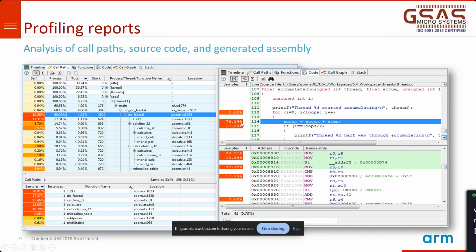So this particular C statement is where the processor is spending 74% of its CPU time. Thereby you can try to optimize this particular C statement and write it as simply as possible so that the processor takes a smaller percentage and quickly executes and comes out. So you can actually optimize your code. Okay.